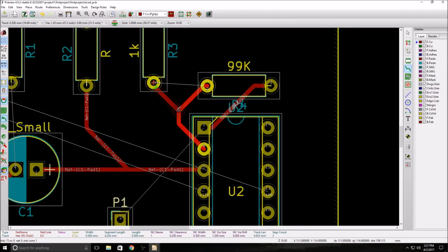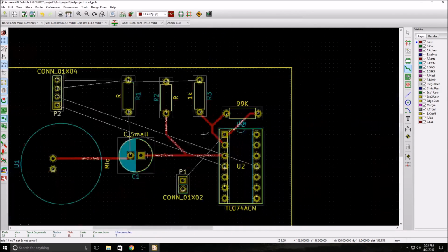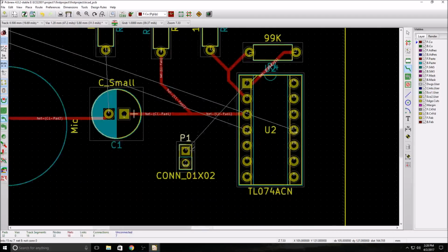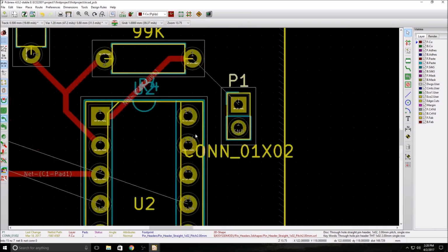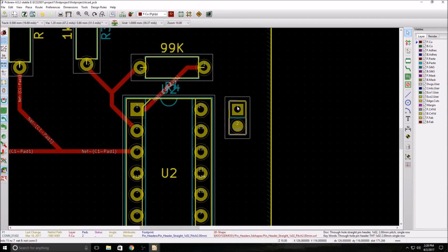We can connect this guy to the same wire, and you always want to do kind of like a branching way so that you minimize ground loops for this. Now you can see here we have an option. We can either go underneath and connect here on the back side, or I can just move this up here, this is where the orientation comes out. I can have them so that I can still route the signal on the same path and it's not an issue. So like I can do this and then I can route it over here.